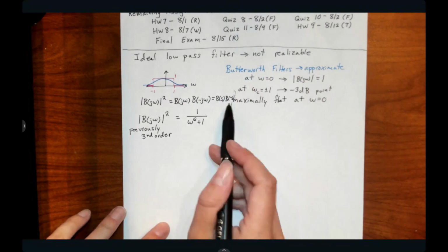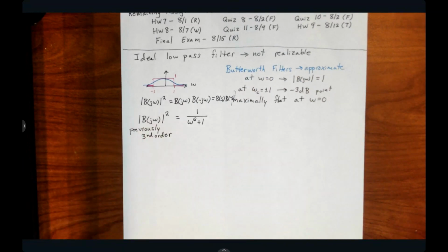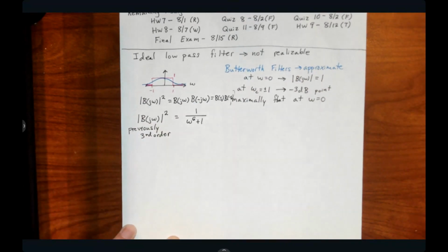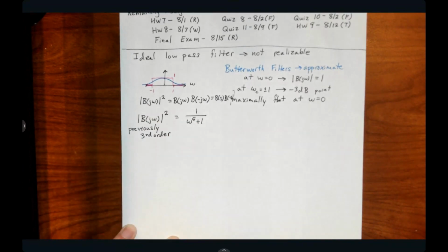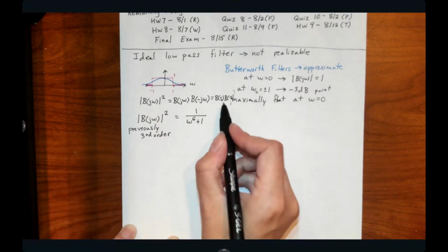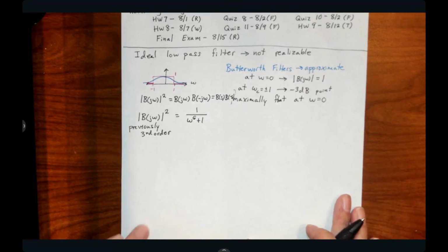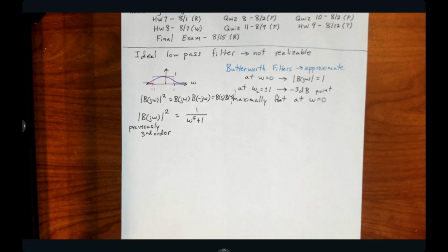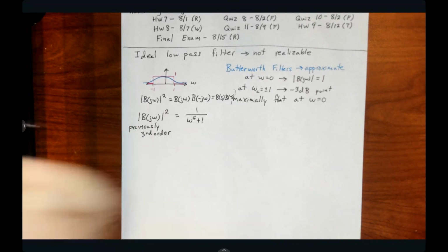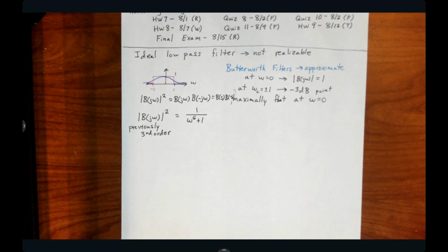Right, so to do this, we want everything to be in the Laplace domain for finding the poles. We're going to find that's the easiest way for us to look at stability of the poles. So we want to convert this frequency response into the Laplace domain. To do that, what we said is that if you have a frequency response like this, a Fourier transform, then you can substitute s for j omega.